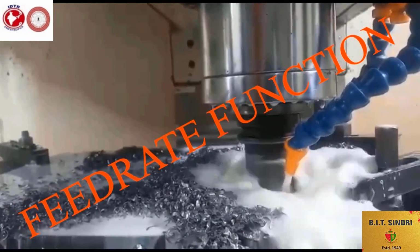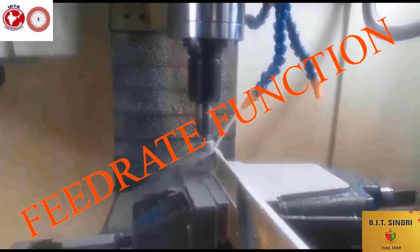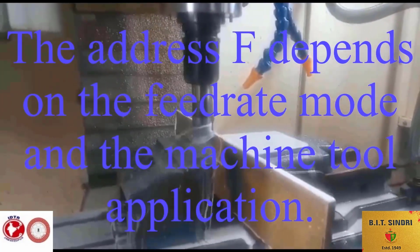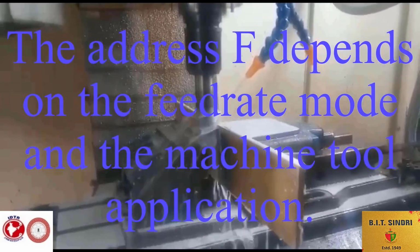The calling address for a feed rate in the program is the address F followed by a number of digits. The number of digits following the address F depends on the feed rate mode and the machine tool application. A decimal place is usually allowed.